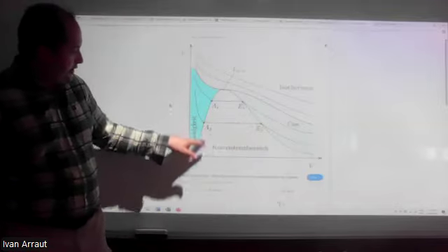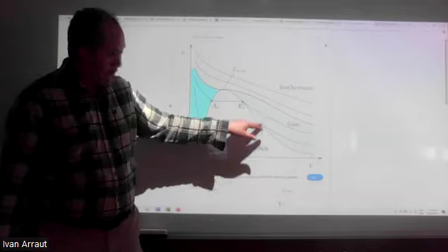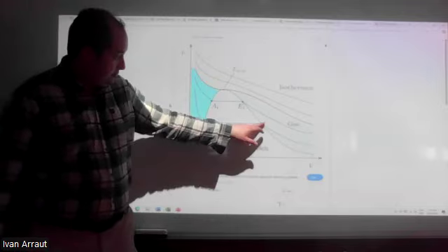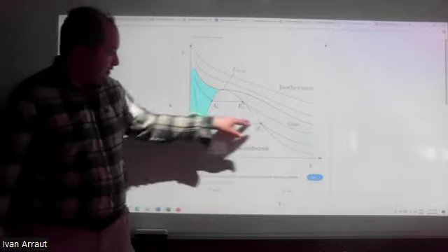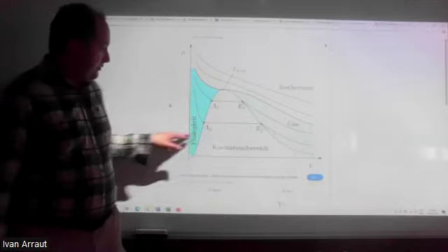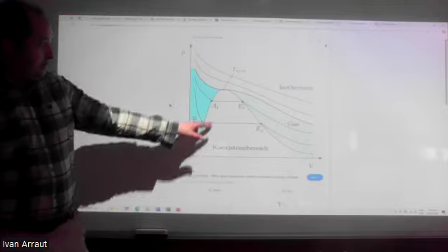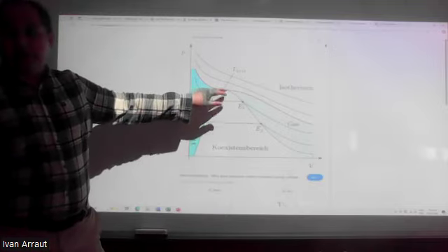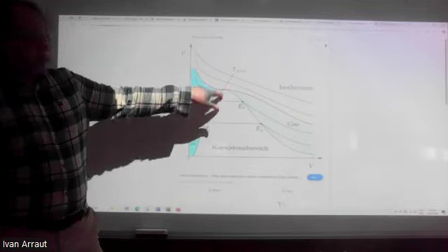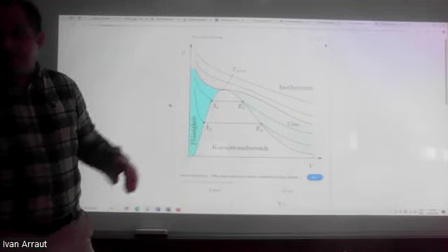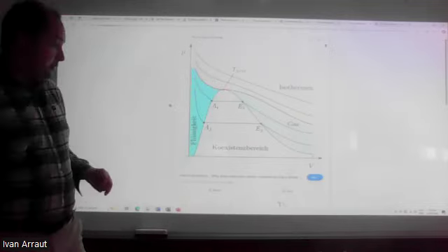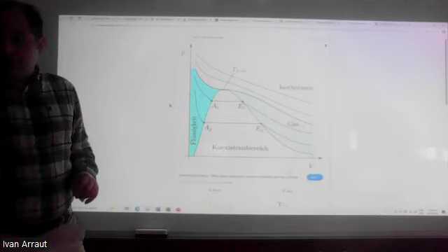The volume here is much different to the volume here, becoming gas. But during this transition, there is an input of heat, of course, and this is called latent heat. If you reach this point, this is a critical temperature. And after this, the phase transition is not first order anymore, it's second order. We will not see the second order phase transitions.